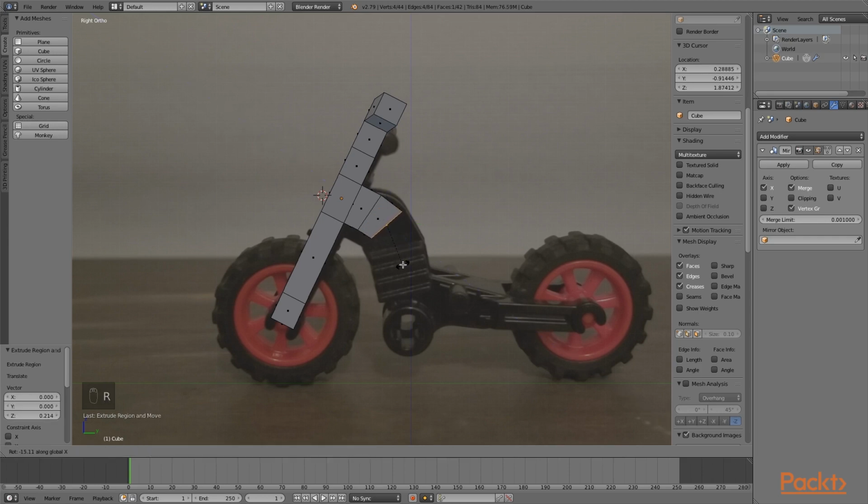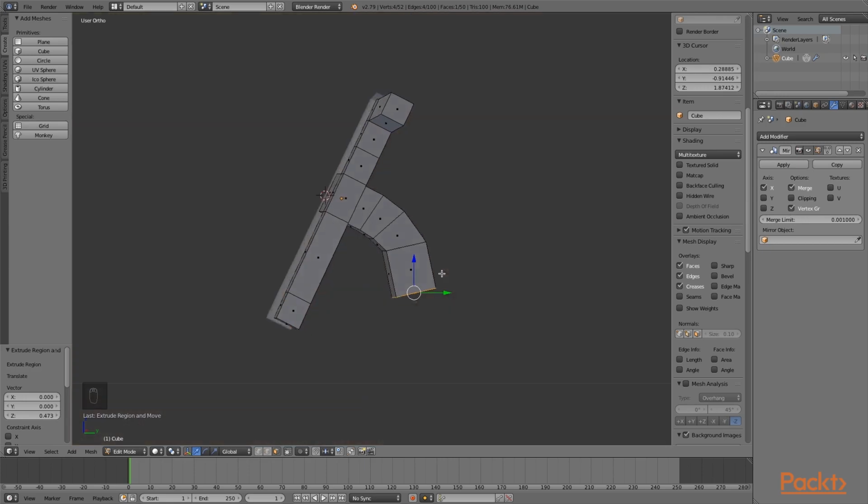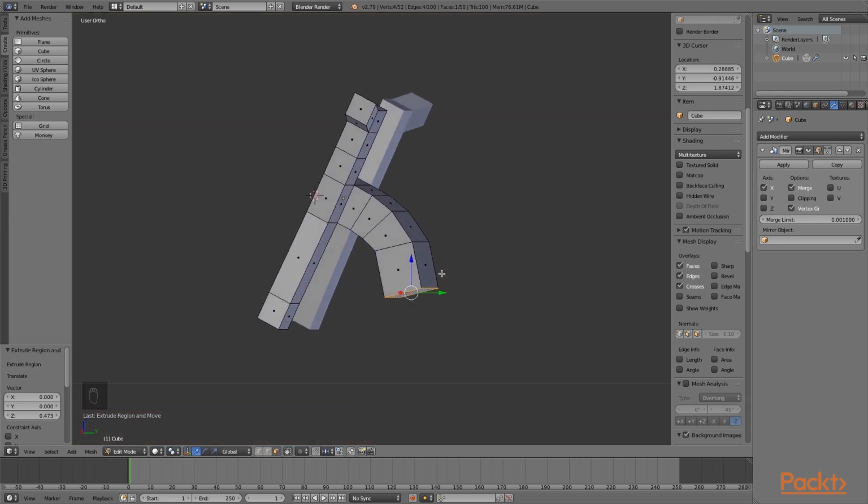So I'm rotating that face again, extruding a little bit more, making a little bit more vertices. So we can bring that out a little bit, rotate on the x-axis, hit X for x-axis and bring it down. And here we go. Definitely a little wider, which we can extrude out a little bit more as we get farther down. But this is going to be kind of the gist of the engine block here. So now you can kind of see that come into life.